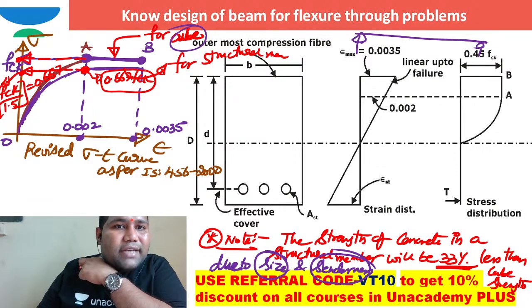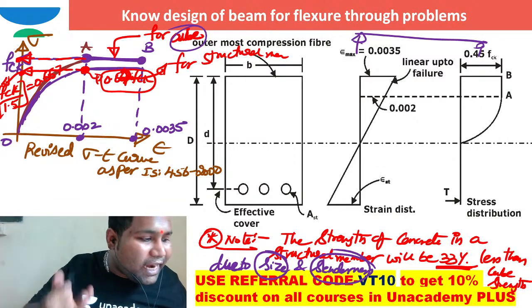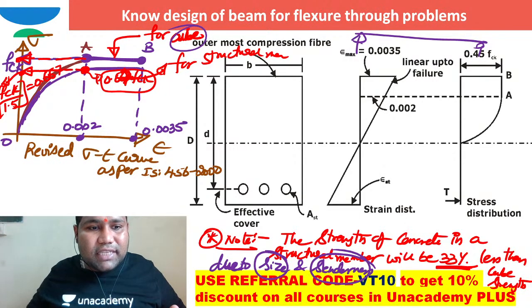The strength is 0.667 FCK, or 0.67 FCK if you take. The structural member has dropped in strength by 33 percentage. Indirectly both are one and the same. How did you get that? By taking the effect of shape and size factor.